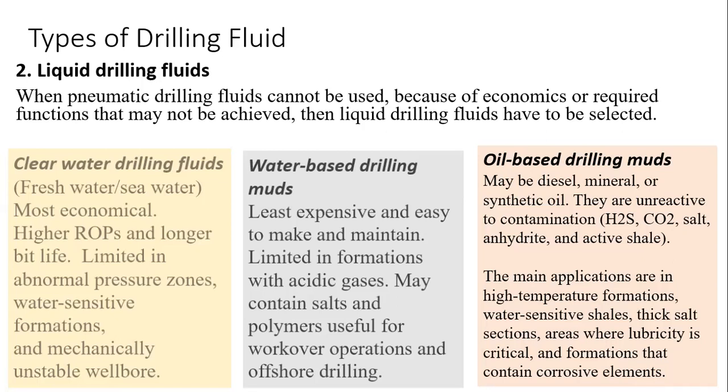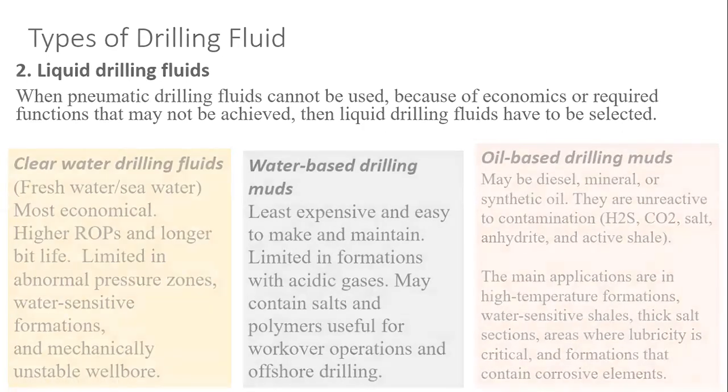So when we are using this fluid in zones like active shale, it is very advantageous because it does not react with the formation. It's mainly applied in high temperature formations and water-sensitive shales and the rest. It also prevents corrosion during drilling.